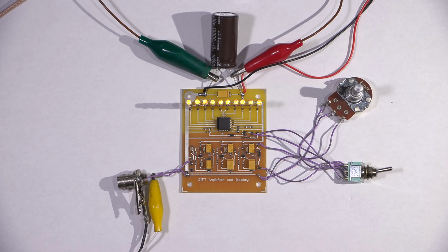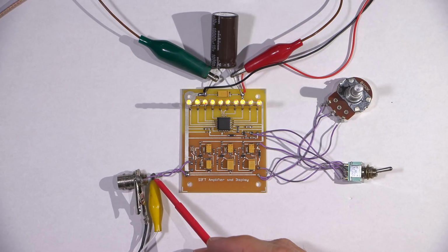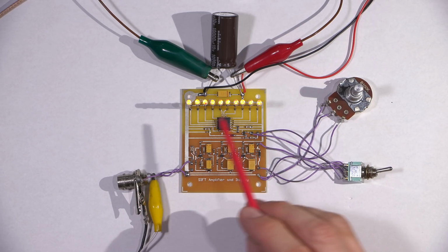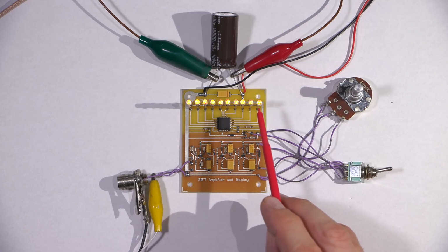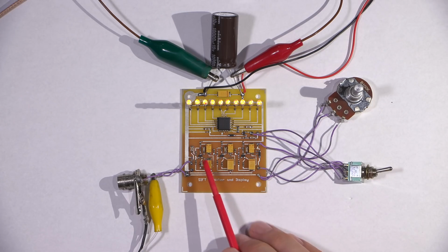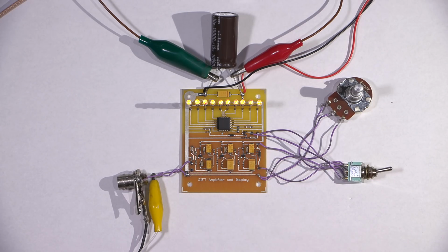So what I'm going to do is hook up my spectrum analyzer now to the input here. Basically, it's going to read the signal coming out of my signal generator right at this point here. We'll take a look at the level of signal that it takes to make this bar graph go right to the top here. Once we've established that, we can write that figure down, and I'm going to show you how to do the math to figure out the gain of an amplifier section like this as well in this video.